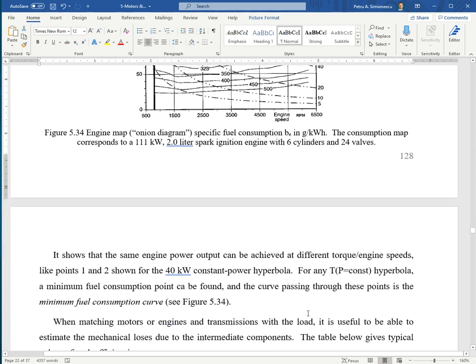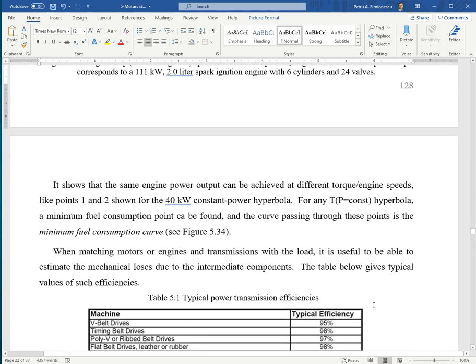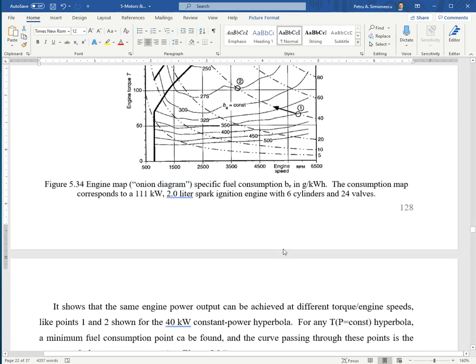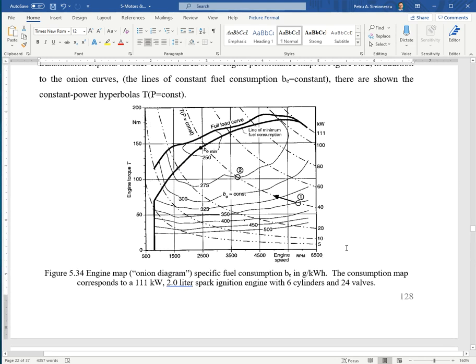Okay, and these are important. Again, when you have transients driving in the city, accelerating, braking, but when cruising on the highway, these are clear to define. So choosing the transmission and final drive such that I'm running close to the best, at partial throttle, close to the best specific fuel efficiency, is how you save on fuel.